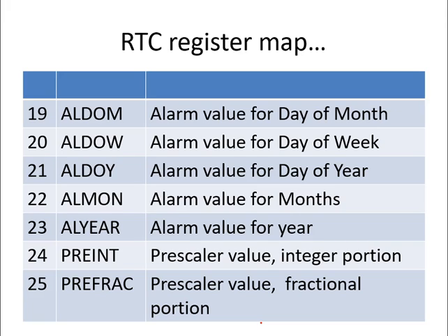So you can roughly say that you have two registers related to controlling the RTC, that is CTC and CCR. Then a bunch of registers to store all the values related to the time, like seconds, minutes, hours, and other things. Similarly, to store the alarm time, you have a group of registers present there. And then we go to the last two registers, important registers rather.